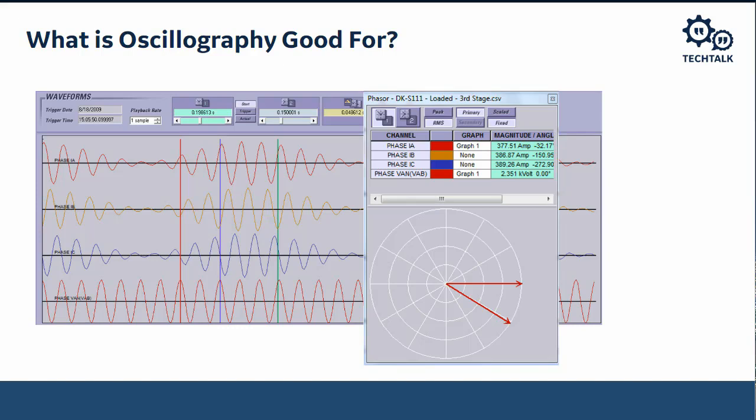What I'm going to show you here, and what I still use, is the free viewer that comes with UR Setup. My colleagues and friends all think I'm old school and say WaveWin is better, but I've never not been able to use this to bring an event to conclusion. So I just use the normal version of UR Setup. It's a Comtrade viewer. It will open and view any event record that uses the IEEE format of Comtrade. Just about all of the GE relays use that IEEE format of Comtrade.